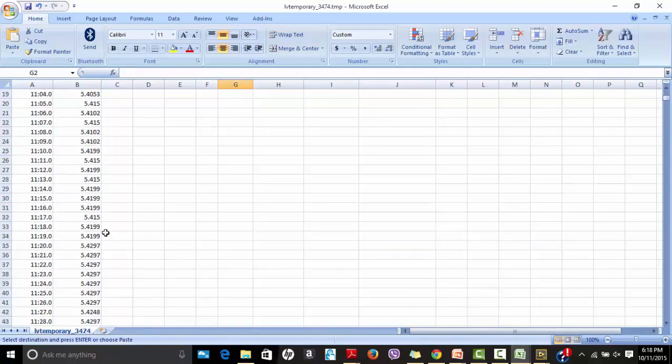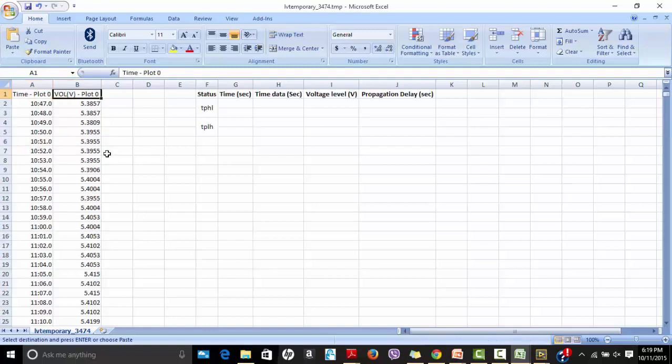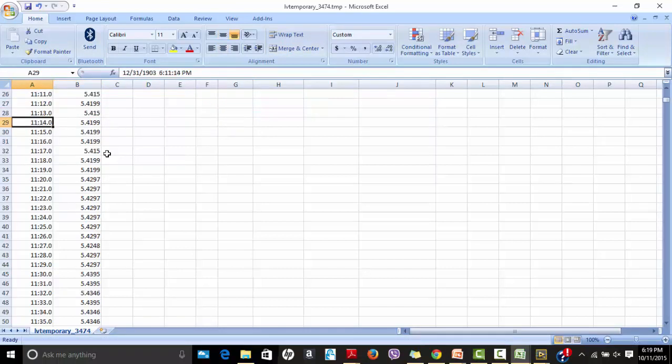My main concern is to look for a value of 5.45. I can see 5.49 here, which is the closest approximation to 5.45. So at 11.53, my output is at VOH. Now I need to see the drop from VOH to VOL, which I can see at line number 156. At 13.21, I can see that VOH has dropped to VOL. I'll copy this timestamp over here. This is for high to low. Now I'm supposed to look at low to high. So I saw VOH at 150.